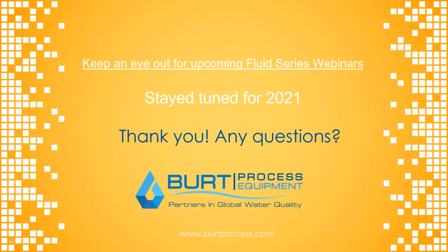Typically, one of the bigger things isn't so much heating, it's actually cooling. If you put a modified storage container with a system outside, for example in the southeastern U.S. with the sun baking on it all day, it's really more of a concern of air conditioning and ventilating the system, which comes up more and more often. The other thing that comes up occasionally is venting. That's a big one with a lot of the hazardous storage, where they actually need a separate vent-based system, in addition to just the environmental controls, based on potential off-gassing out of your system.